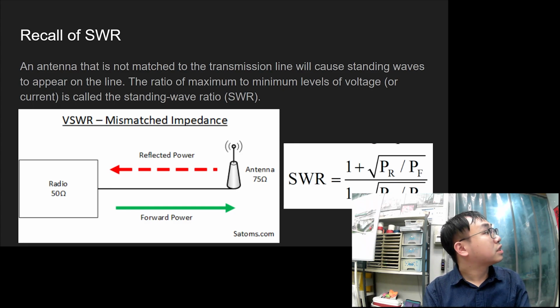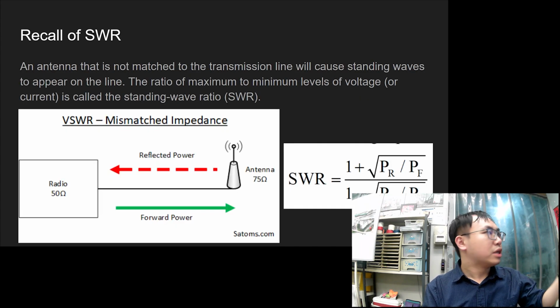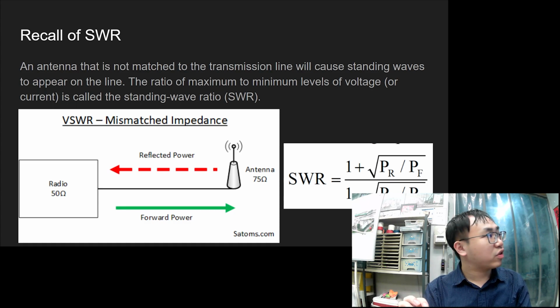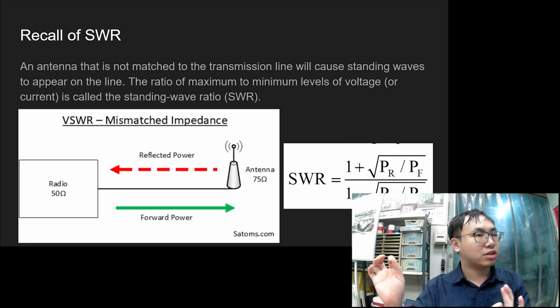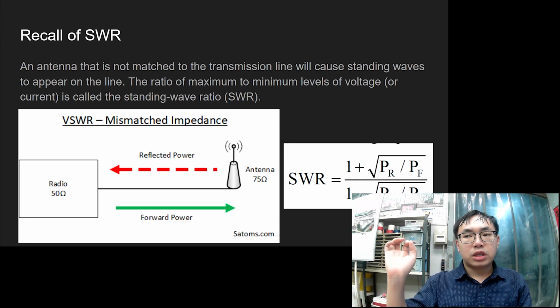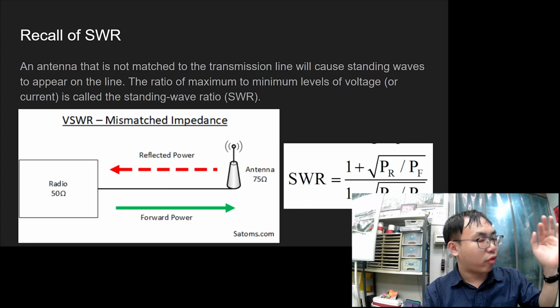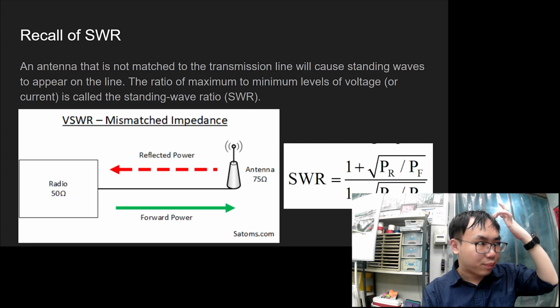Yeah. So the SWR is for you to okay. So when your antenna is receiving at the target frequency, it will have a very, very low SWR, and it's 50 ohm. But when the antenna is not receiving the target frequency, the impedance will change. That's why the SWR is no longer 1 to 1 or 1 to 1.4, a very low value. It will increase to like 1 to 2, 1 to 5.